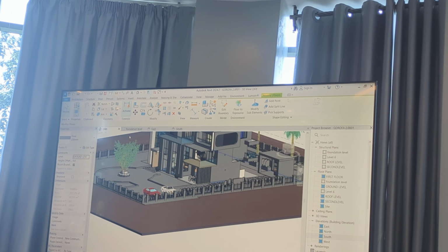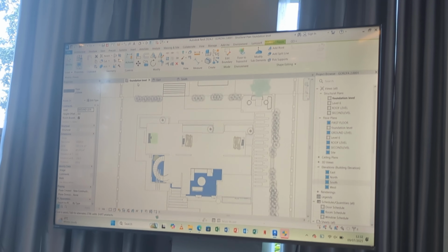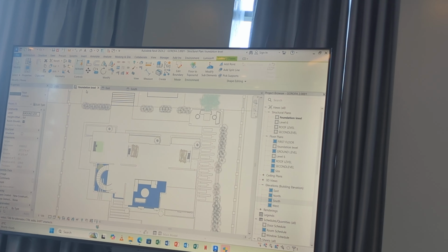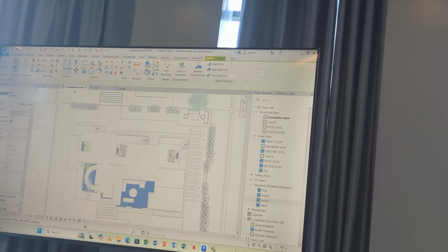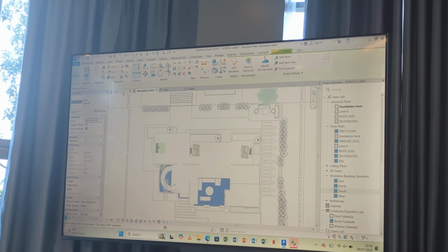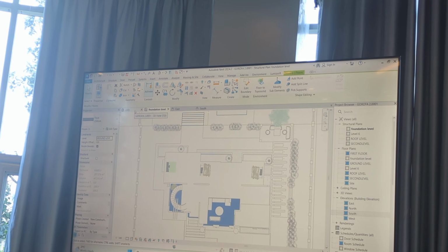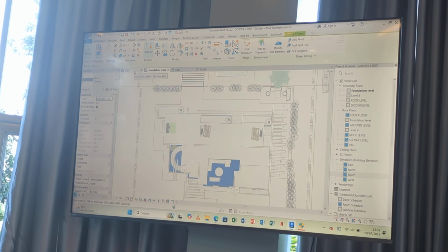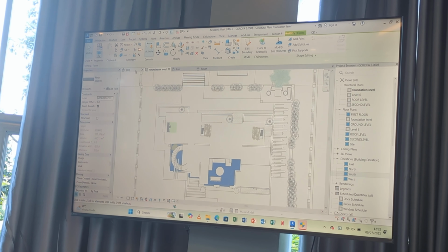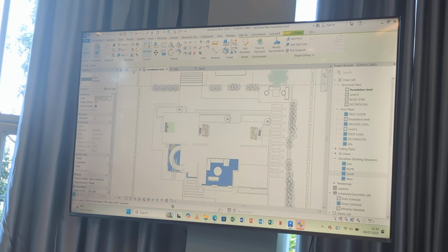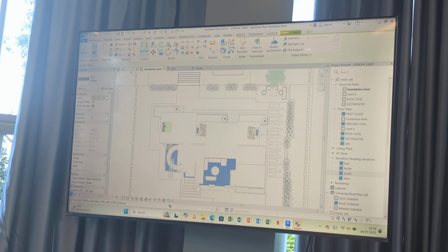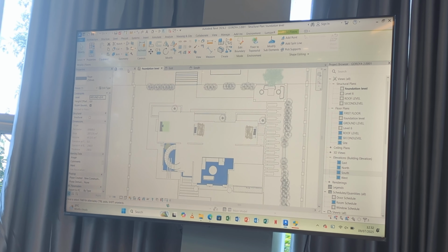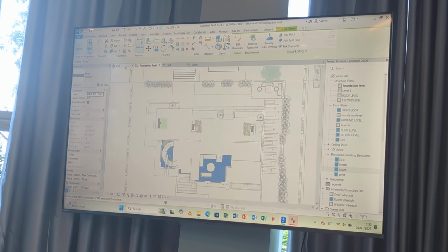So that means my wall is going to be 1.3 because my foundation level is starting at 1.5. I hope that is making sense. For people who are more confused, yes, we are confused. Why are you confused? I used 1 meter there because for my slab I had used 500 with everything combined. So for this, my foundation is still starting at 1.5, but my slab is 200. Hence 1.3. Yes, minus the 1.5, minus 200, is 1.3. Okay, 1,300.